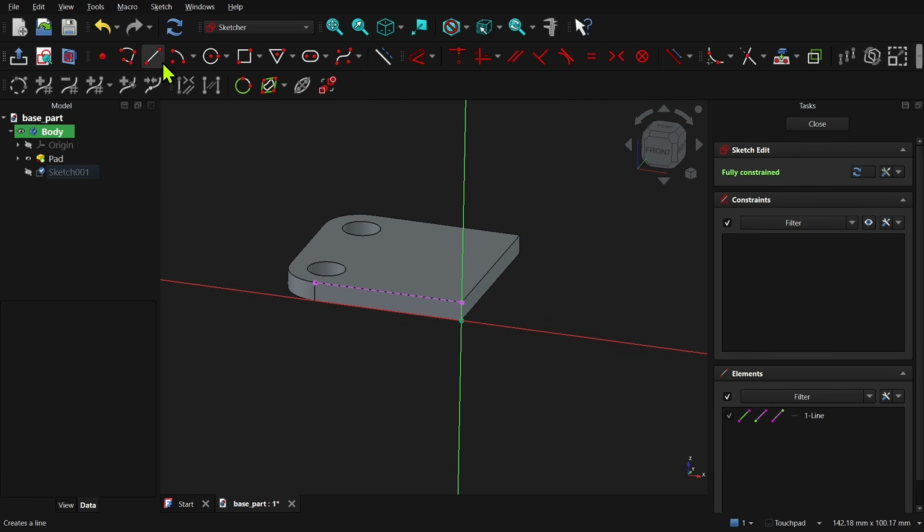Before proceeding, make sure the top tools are in white. If they aren't and they're in blue, make sure we have no geometry selected and click on the Toggle Construction Geometry button. Now let's select the Polyline tool. Use the View Sketch icon to reset our view.